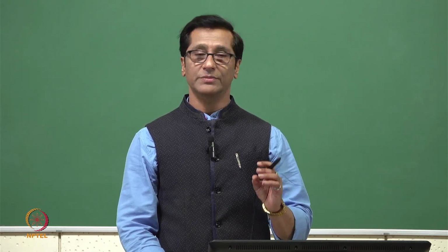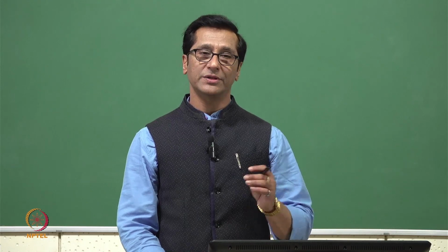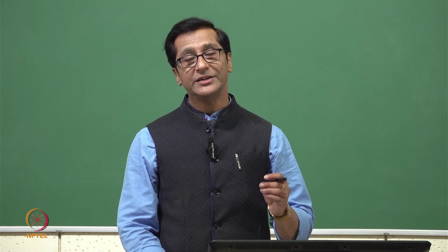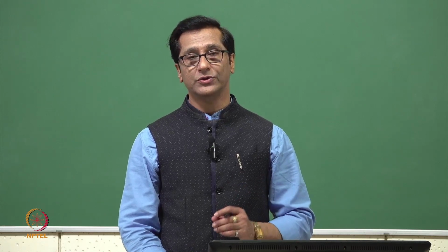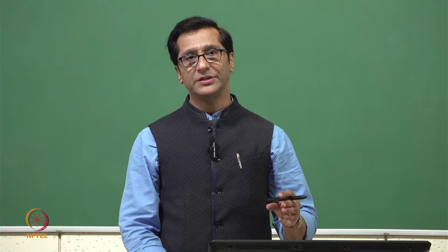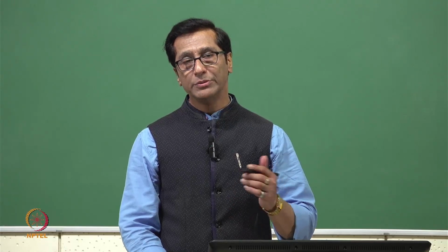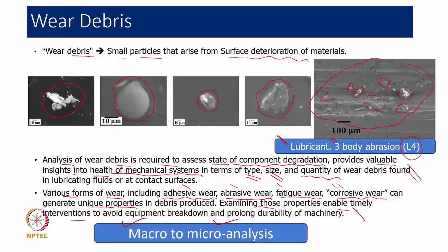Maybe there's a misalignment, or the oil choice is bad, or the oil additives have degraded, so we can change the oil also. Those corrective actions can be implemented if we know this kind of information.